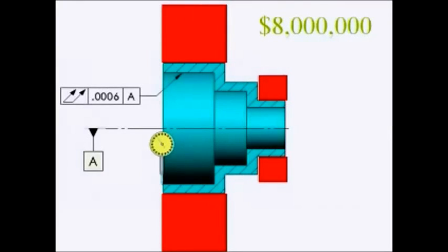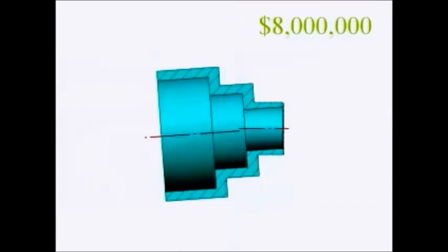The problem is that each cylindrical feature of a part has a different axis. Holding the part differently gives different results. Heck, if parts could be made perfect, there would be no need for tolerances on drawings. So we must make it clear on a drawing which features to use to establish a datum. This way, the drawing makes clear the design intent.